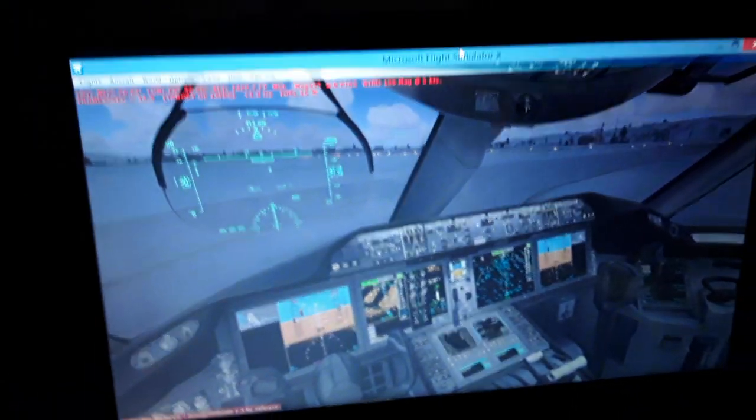This is the LSZH localizer. We're also going to have the flaps extended to 25, 30 degrees, about 60 or 70% of engine thrust for approach and landing, 160, 170 nautical miles per hour airspeed for approach and landing, and also the landing gear extended. So you see the complete flight and also the complete flight plan over here.